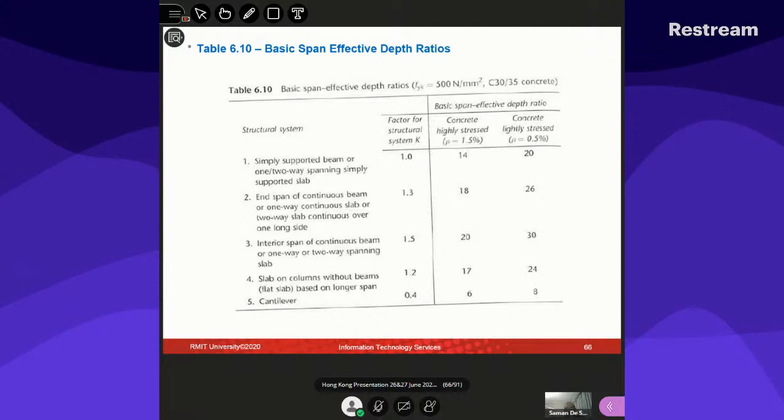Once the floor framing is done, without jumping to the numbers, from an argumentation point of view, with the knowledge that you have, like span to depth ratios, span to deflection ratios, those types of broad values, you would be looking at it first qualitatively. You start to think about the problem and get the best framing proposal.